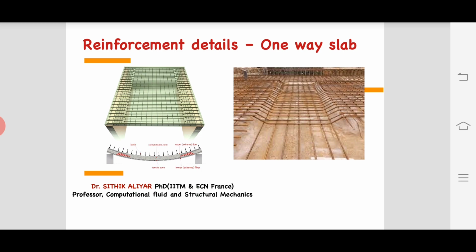So slab design is nothing but you have to tell the bar, and even the bar is constant, you can note it somewhere. So even though everything is known, nobody is going to ask you, only maybe in an interview they may ask you. So for the overall slab for the room dimension, depth is 100, 150, 175, 200 based on the load coming above, only this much thickness will be there. And the reinforcement in most cases is 8 mm or 10 mm, and spacing will be most of the cases 100 mm center to center, or 125. Okay, I hope you don't get confused. I have told you the answer. Slab means this is your answer. Whatever question they ask, this is your answer.